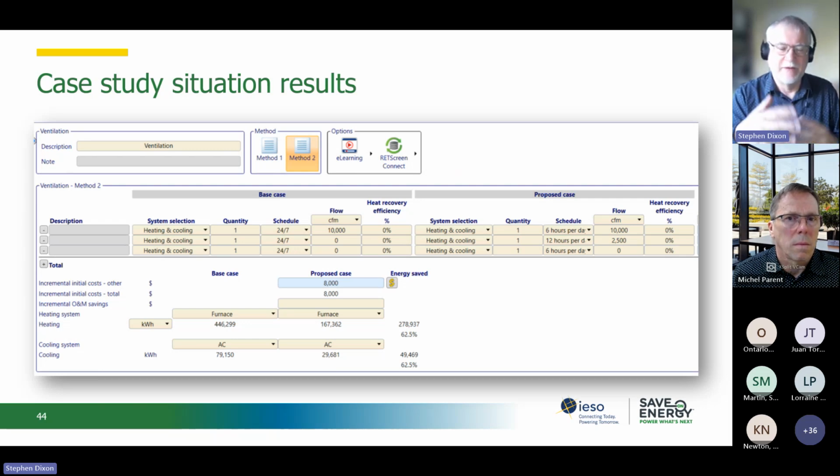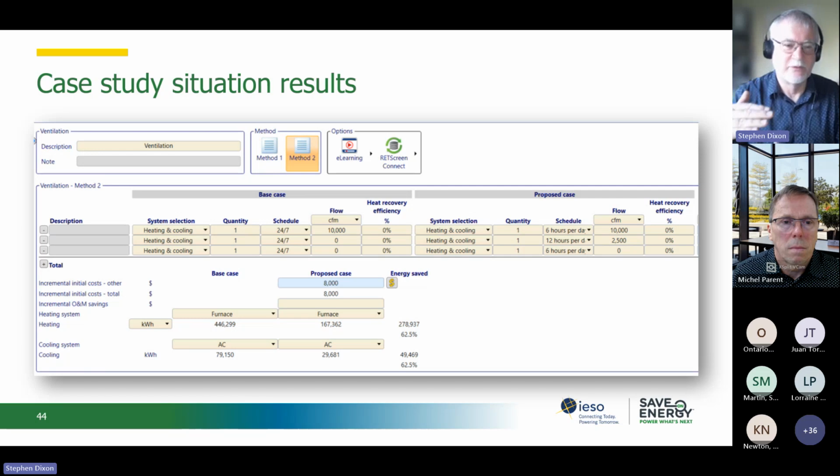It's not going to be a 2-speed fan or something like that, on, off. It could be on, off, and then lower speed. So you could have a 3-speed situation, but typically today, Michelle, this would be implemented with a variable speed drive and a sensor of some form over in the stove area. So you're basically modulating, but we're going to approximate what that modulation looks like with 3 different modes.